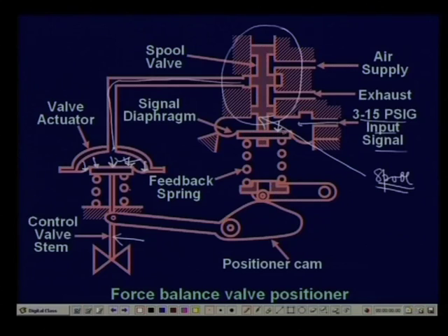That creates a force on this spool, which will move downward. When it moves downward, the high pressure air supply will flow through this and come here. Depending on the opening, there will be a kind of pressure drop, and the final pressure will be realized here. Now, as this pressure increases, this thing starts moving downward and the valve opens.